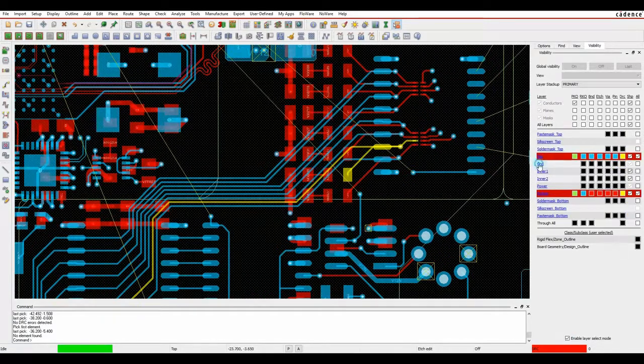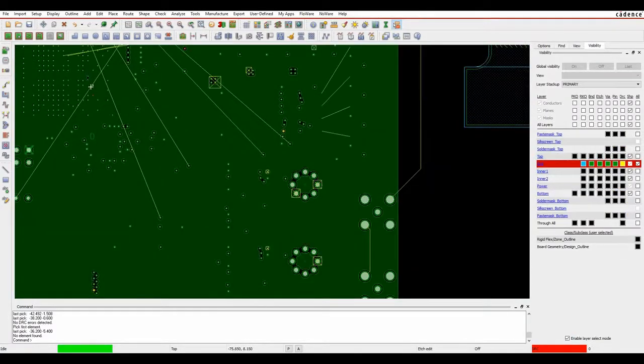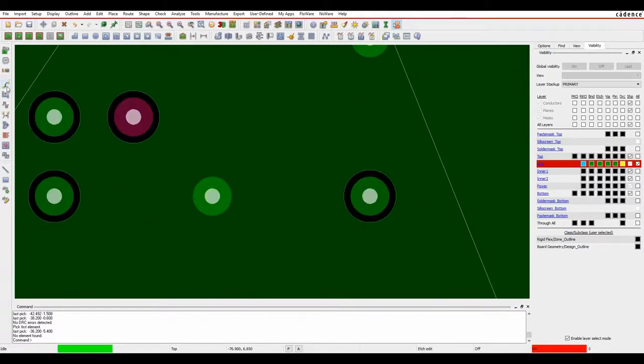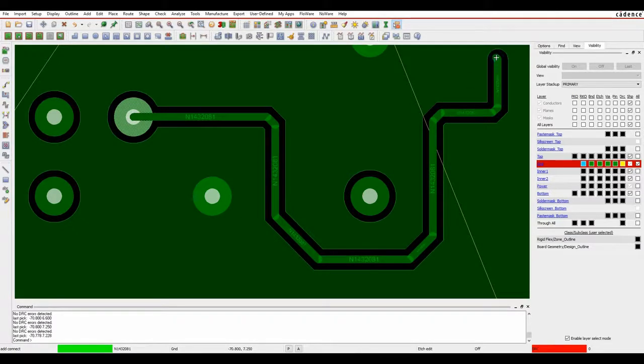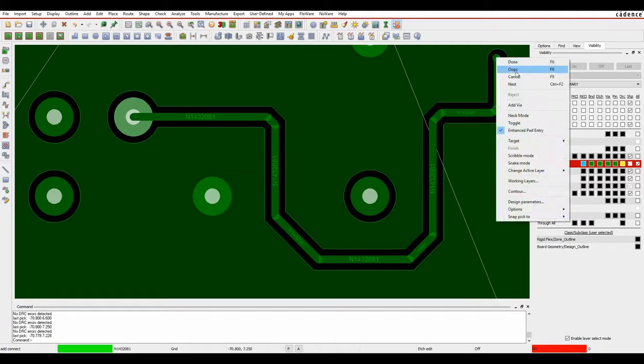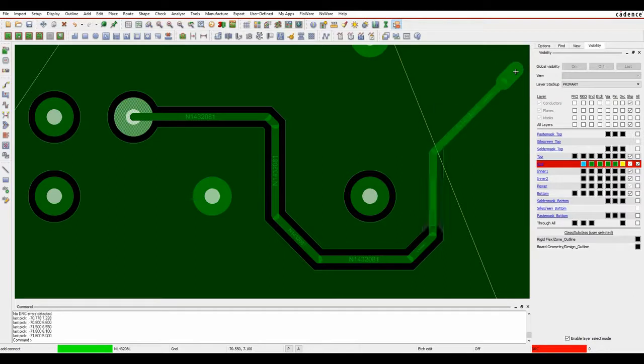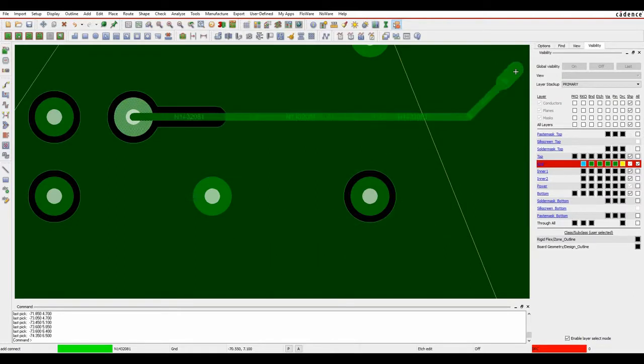We'll go back to the single layer select mode and we'll turn on our ground plane. So we're going to do some routing through a dynamic ground plane. I want to pick this net and start routing, and you can see that the copper shape dynamically updates to make any clearance as I'm routing through the copper. So I haven't got to worry about repouring the copper afterwards or doing it as a post-process. It's all instant. If I've made a mistake, I can literally use a right-click Oops or press the F8 key. So we'll just press F8 to undo those objects, and the copper shape repairs itself.